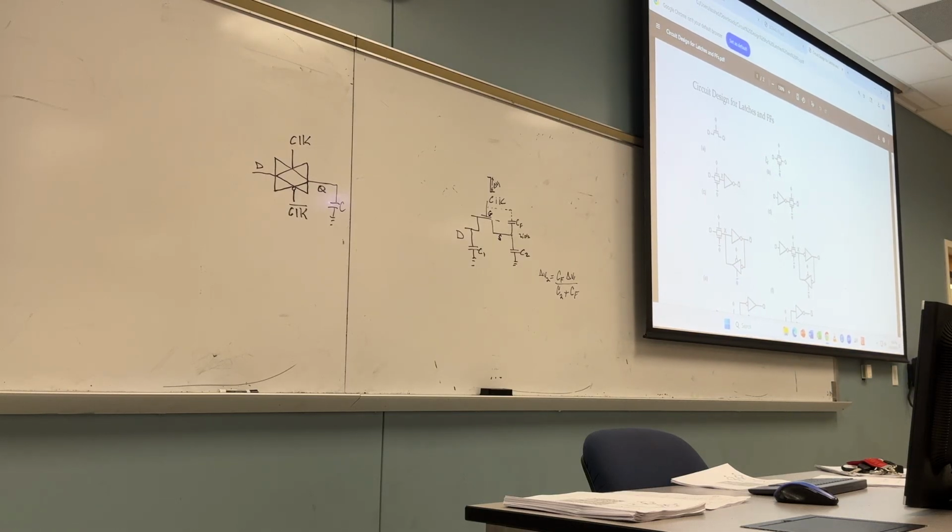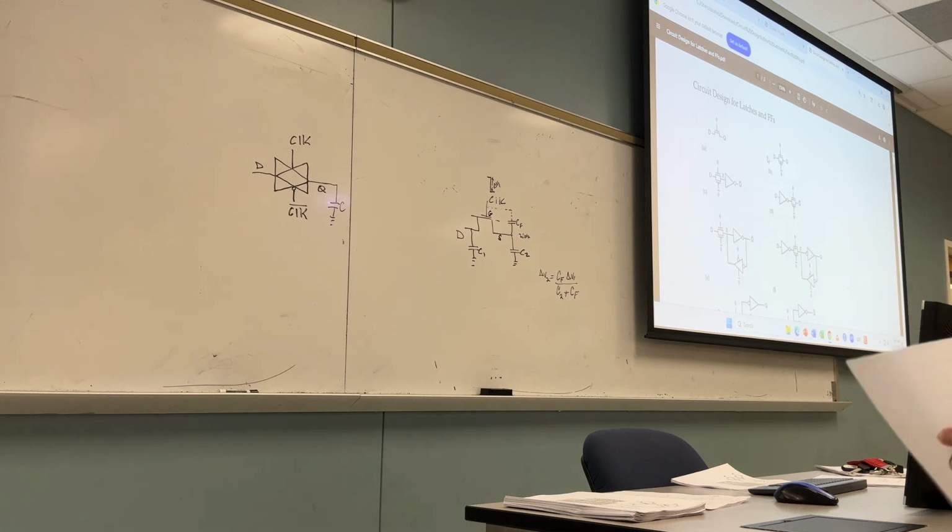Why did we add the inverter? We added the inverter at the output to isolate the state of the latch. You do understand this logic is one directional. You follow me or not? Which means if you do have a NOT gate, the noise cannot go from the output back to the input. It can go from the input to the output. Did you get it? Mm-hmm.